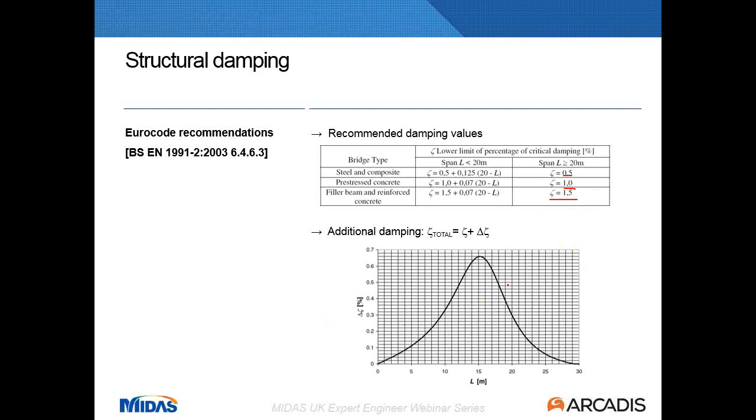Another situation, if you are assessing a bridge that you are able to monitor, and then you can assess which are the damping ratios for mass and stiffness, then you can just use these values from the monitoring that are probably more accurate than these ones over here.